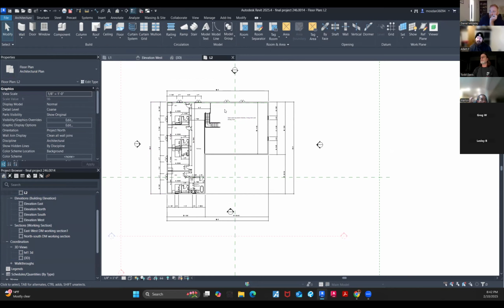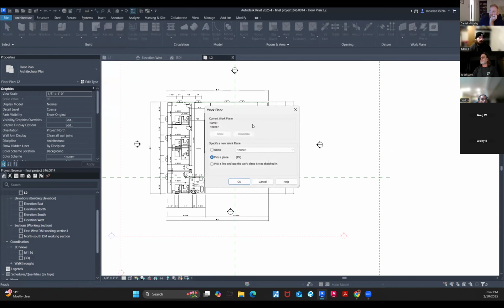So let's go to roof, and I want you to hit the caret underneath the roof button, not the actual roof, but the little arrow button down there. Yeah. Now let's go to roof by extrusion. All right. Right now it says pick a plane, so click your drop down. And we now have the north wall plane that we just made.